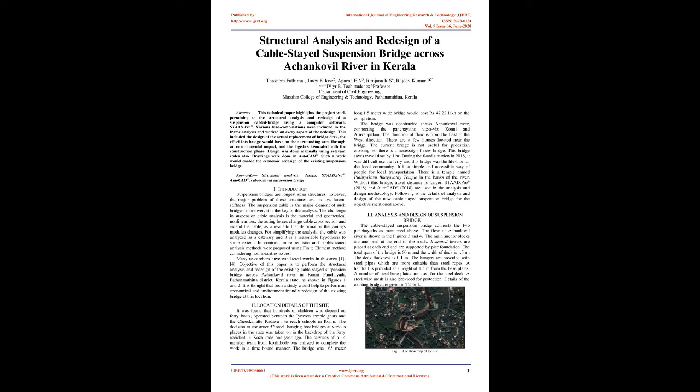Introduction. Suspension bridges are longest span structures, however, the major problem of those structures is their low lateral stiffness. The suspension cable is the major element of such bridges, moreover, it is the key of the analysis. The challenge in suspension cable analysis is the material and geometrical nonlinearities. The acting forces change the cable cross-section and extend the cable, and as a result of that deformation the Young's modulus changes.